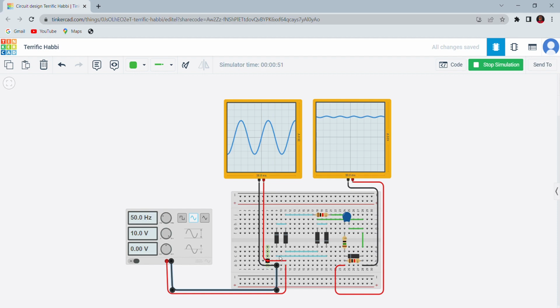And for the negative charge, we can see here, the current will go through the diode 2, and because it was the forward bias, and will not go through the diode 4 because it was a reverse bias. And same, it will not go through the diode 1. Instead, it will go through the resistor, and then capacitor, zener diode, and resistor, which is we have put it in parallel. And the current will go back to the power supply through the diode 4.